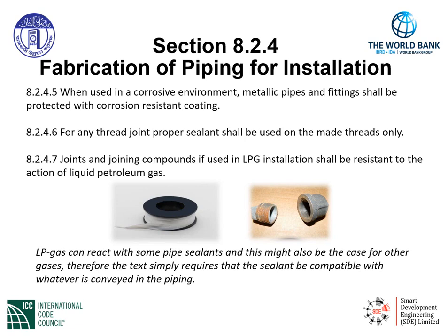Section 8.2.4.6 gives us the requirement for any thread joint, proper sealant shall be used on the made threads only. Therefore, we use it on the threads only.